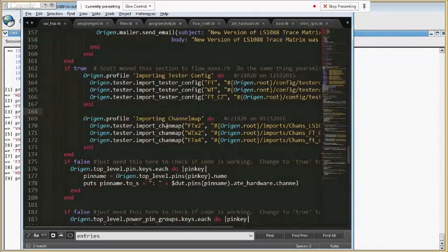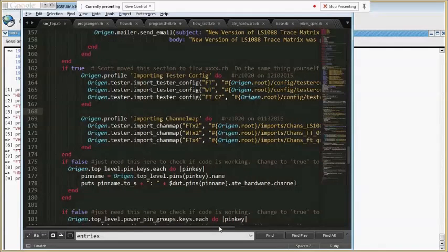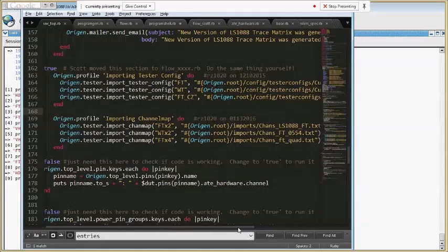The way this works, and this is part of the Origen tester gem, is you go to the tester you're using. This is UltraFlex only. You grab the current config from the IG-XL folder and use that to load it in. The command itself is import tester config. In my case, you can put this anywhere really; I have this in my SOC top. You have the path, and then you give it a name.